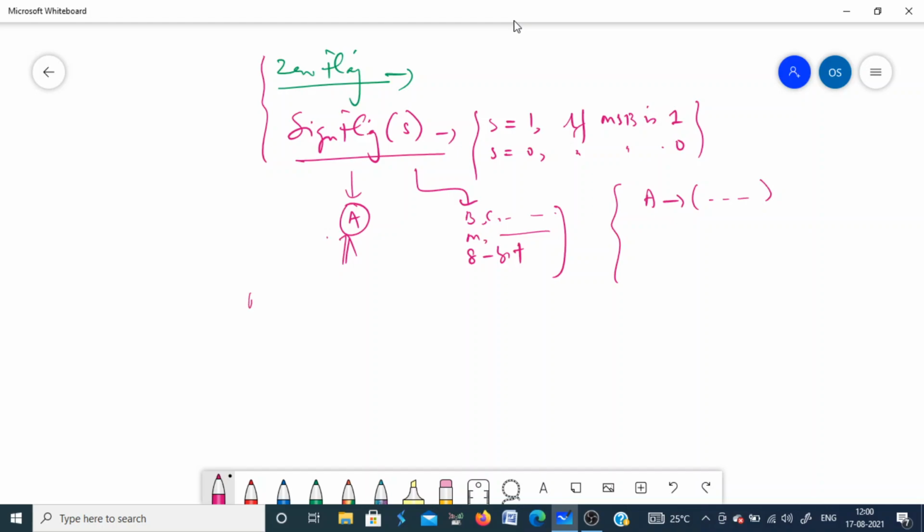A minus B, it can be A minus C, A minus some data in the memory, or it can be A minus some 8-bit number directly. And after this, the result is, of course, again stored in A.